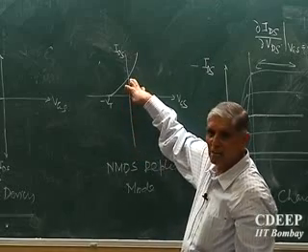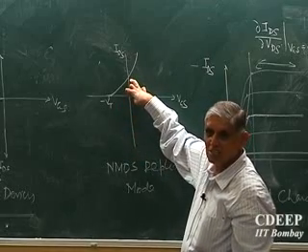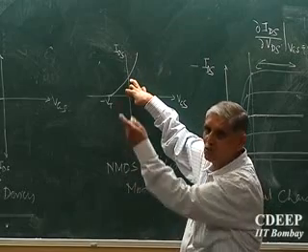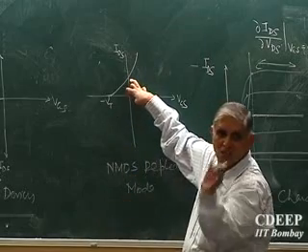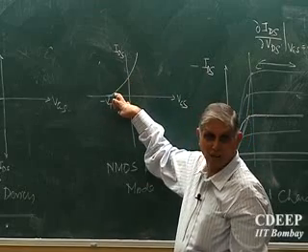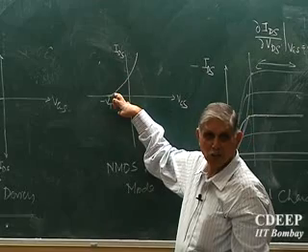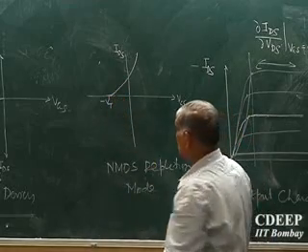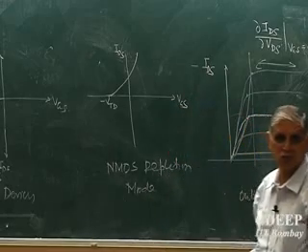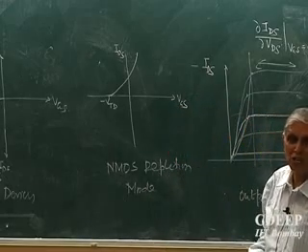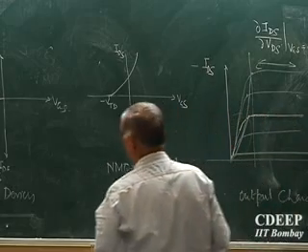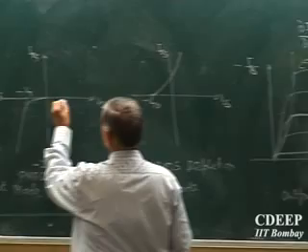Even at zero bias there is a current. Even at zero bias there is a current, because you have put an N region there, no? That current is flowing there. To shut it off, deplete it off, I will require a negative VT. This is many times called VTD, depletion device VTD, which for N channel is minus. For P channel, where should I draw here?